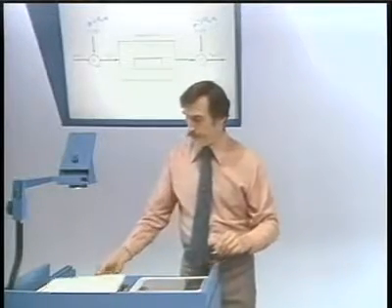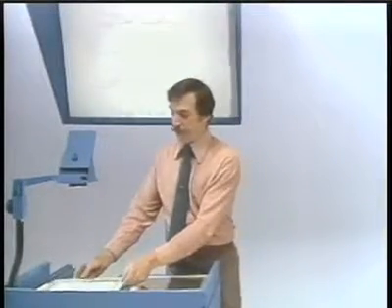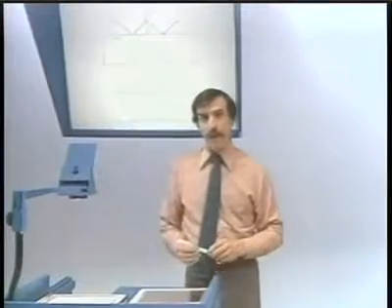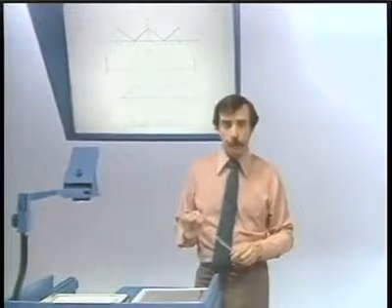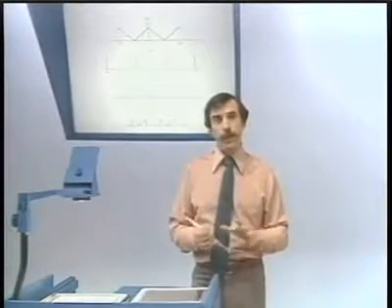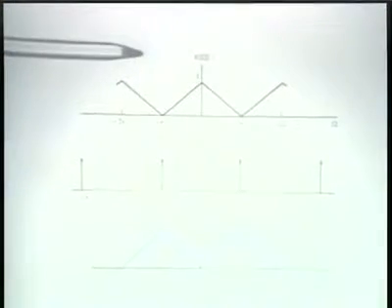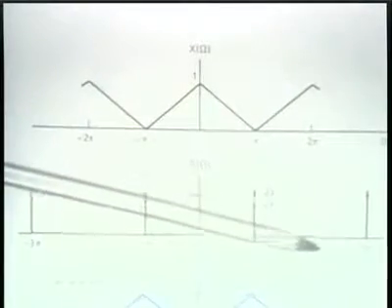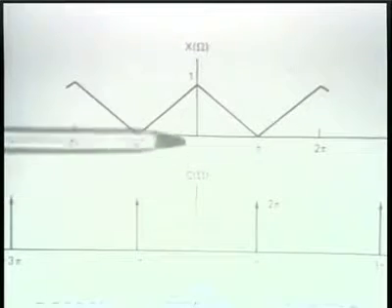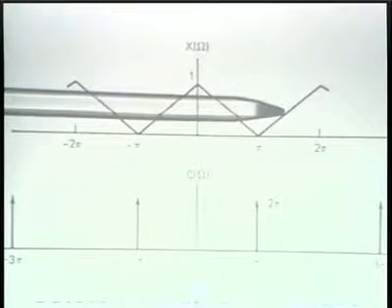Well, let me continue the review of that just by reminding you of the details of what happens with the spectra. And specifically, if we take this particular case of ω_c equal to pi, or equivalently a carrier signal which is (-1)^n, then if we have the original spectrum and the spectrum of the carrier signal, the spectrum of the carrier signal convolved with this spectrum will, in effect, shift this by pi.